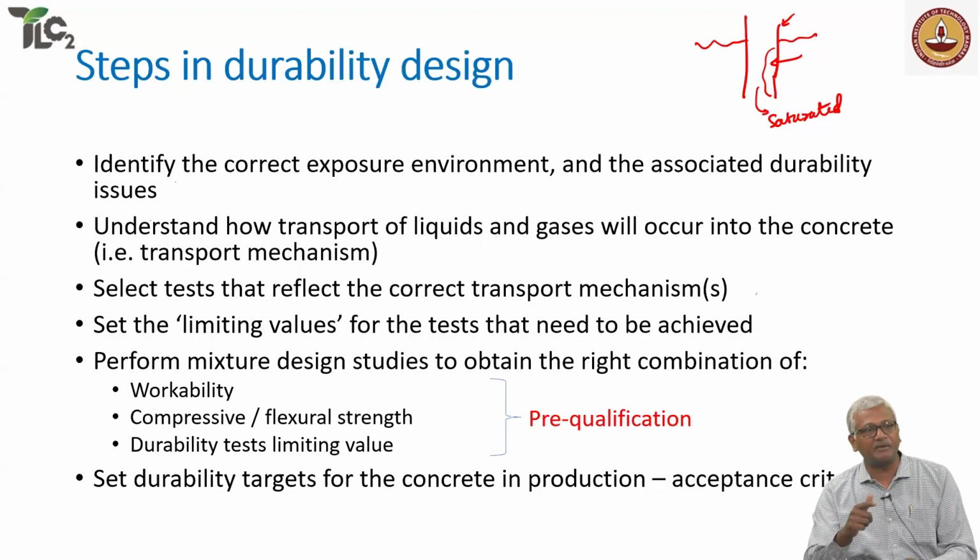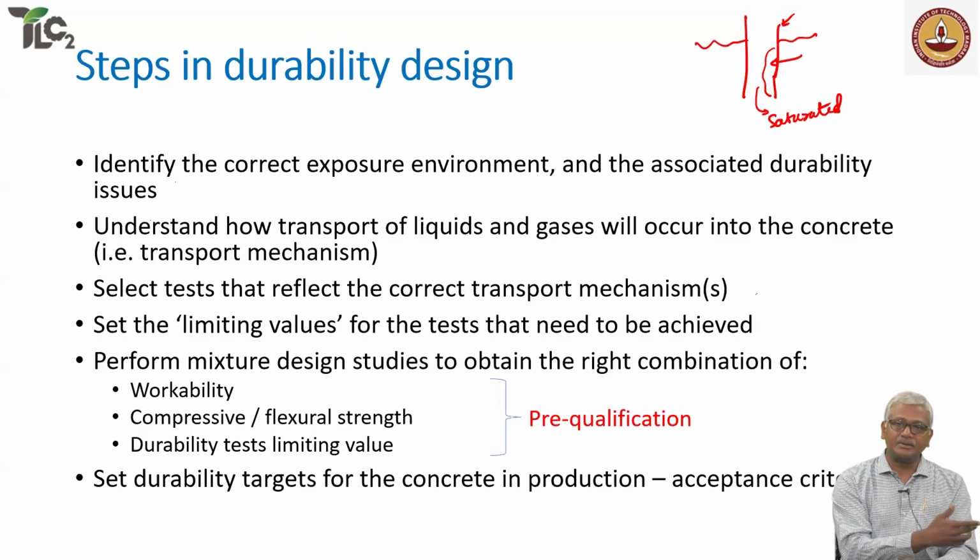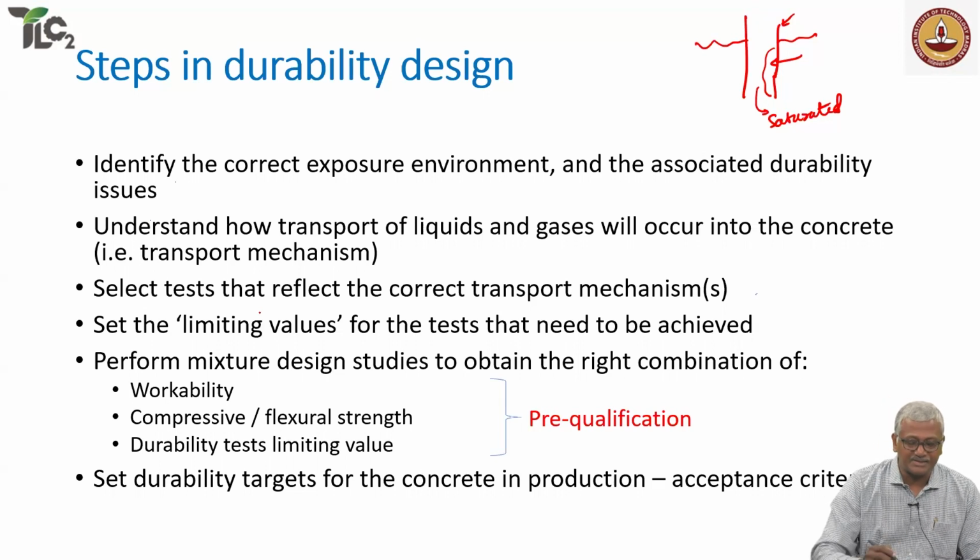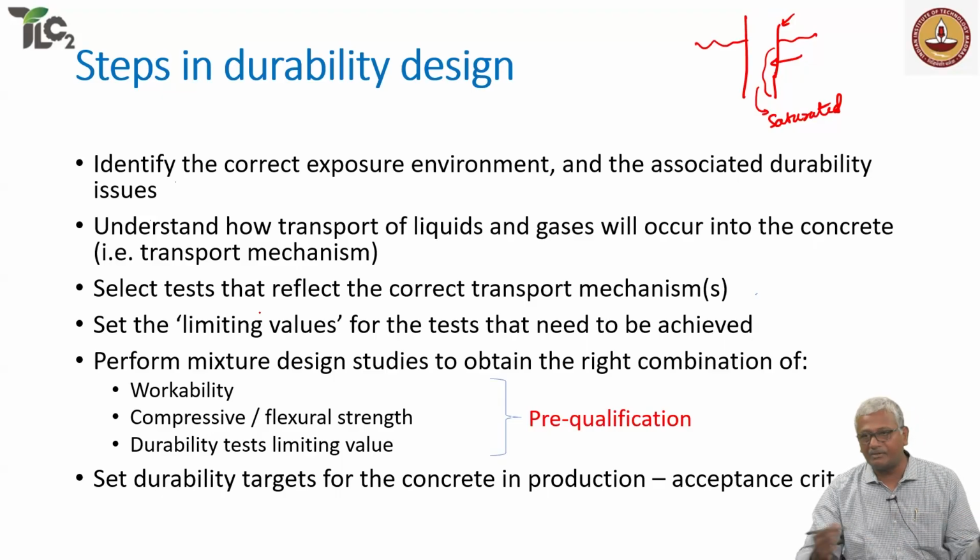So you need to be aware of how these liquids are getting transported, and your test methods have to address those transport mechanisms. That's why I was saying the choice of simply using RCPT and WPT in all our projects is not a good idea, because it's not really paying attention to this aspect. Okay? So understand how transport will happen in the concrete and select tests that reflect the correct transport mechanisms. We have a range of tests available.